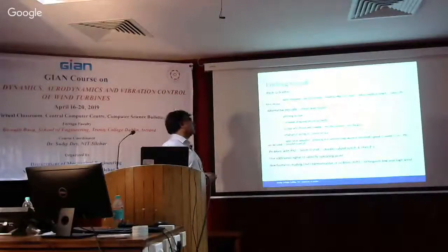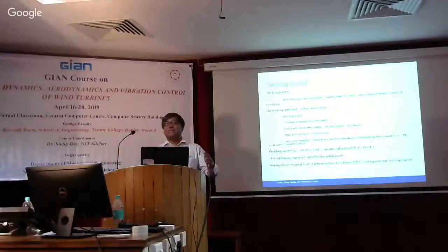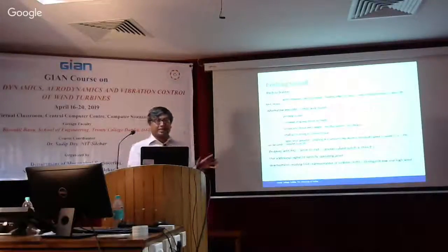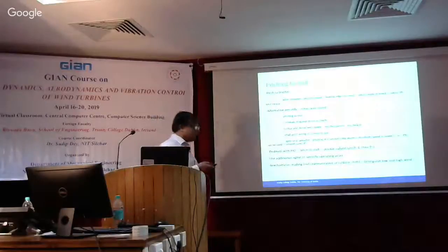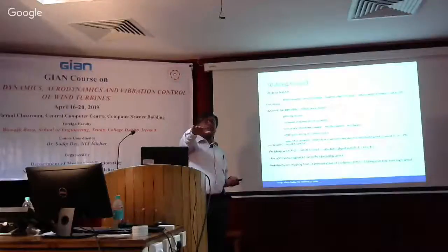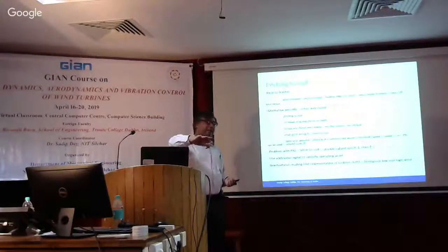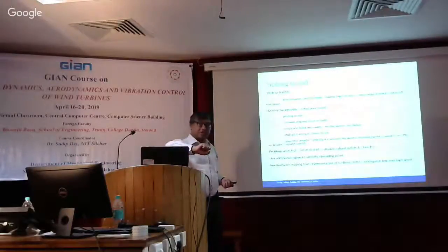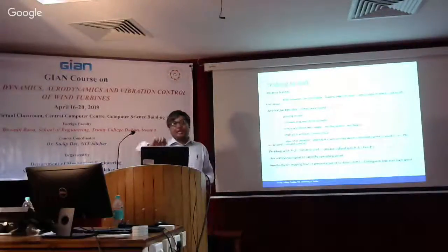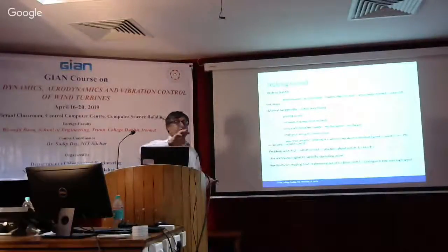Another thing to mention is pitch control also can be used for stalling, in fact. So what I'm saying is that you can see the use of pitch control for various different things. It can also be used for stalling. What it does is the pitch can actually feather the blade out of the wind, and it's kind of cut out, basically, in the direction of the wind. And as such, what happens is that there's no torque produced, and then essentially you can put the clutch and the blade can just be free. So there's no stress on the actuator or the pitch as well in that case.